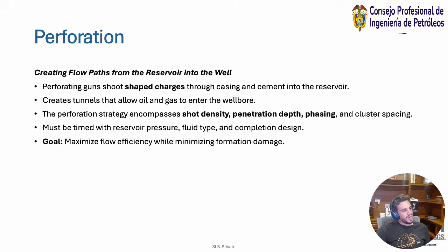And the perforation strategy is based on the shot density, the penetration depth, the phasing, and cluster spacing. But this is basically knowing how your perforation should take place, and also the patterns that I talked about. And it must be timed with the reservoir pressure, the fluid type, and completion design. So all these parameters are being taken into consideration.